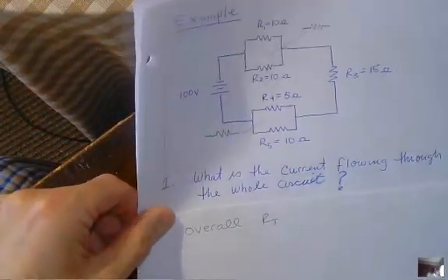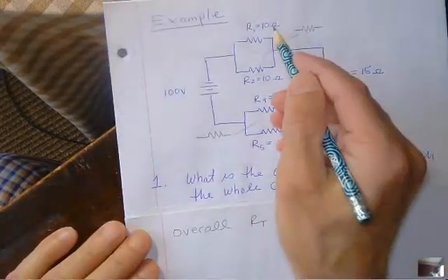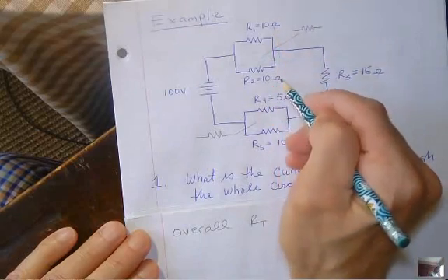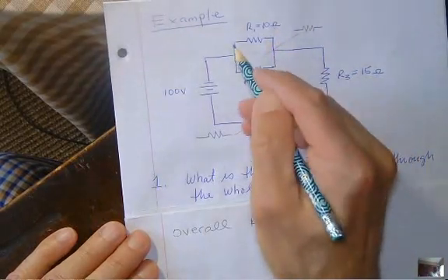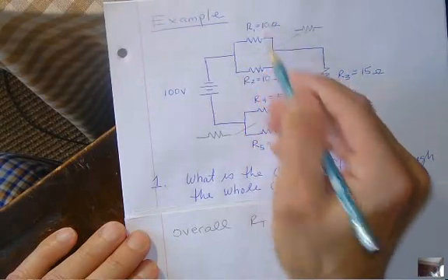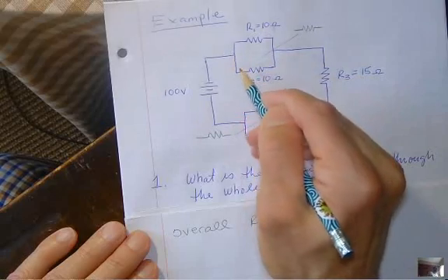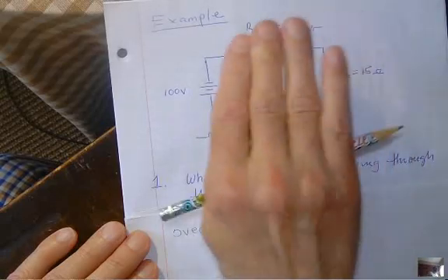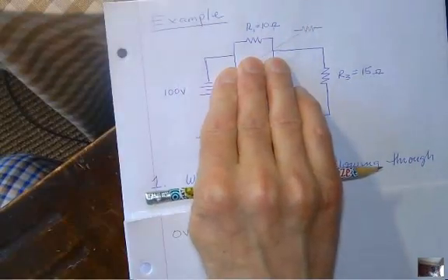So how are we going to find out this first resistance? Okay. Well, I'll tell it to you by hand, and then we'll do the math anyway. Okay. What did we say? When two resistors both have the same resistance, and they're in parallel with each other, the equivalent resistance is half that amount. Because here comes the current. It's got an easier path. You made, by adding the second one, see if I only have one, they all have to go through that way. So that's 10 ohms, that stinks.